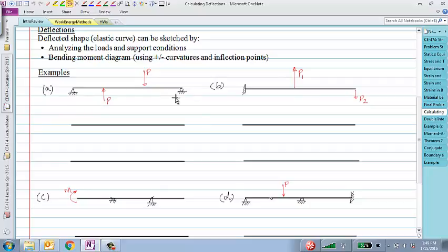We don't know the magnitude just because we don't know the length of the beam and don't know the moment arm between this P and P. But let's say R, okay? Since this P is going down and this P is going up, the beam would try to rotate this way. And to oppose that, we would need a reaction pointing up here and a reaction pointing down here, some value R.